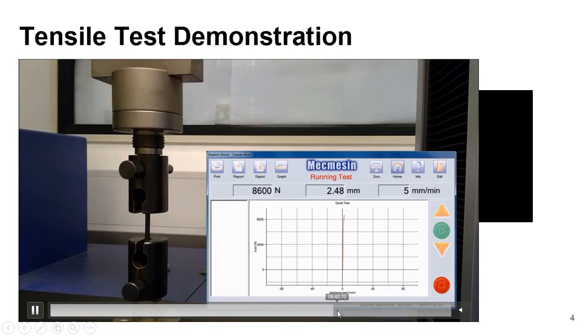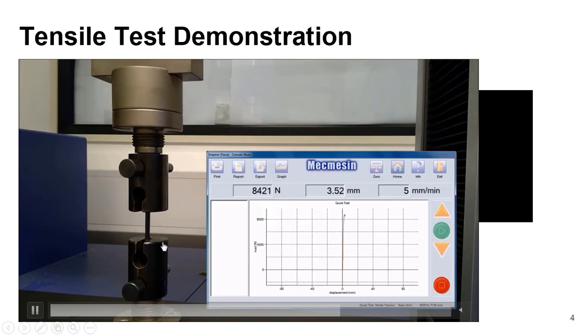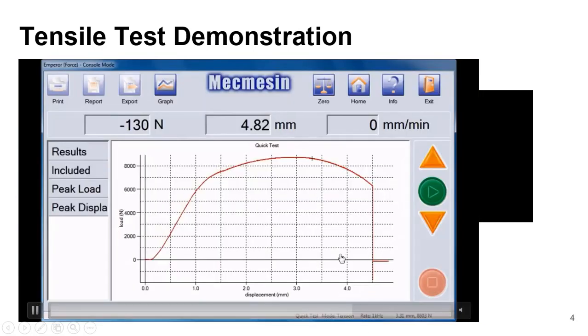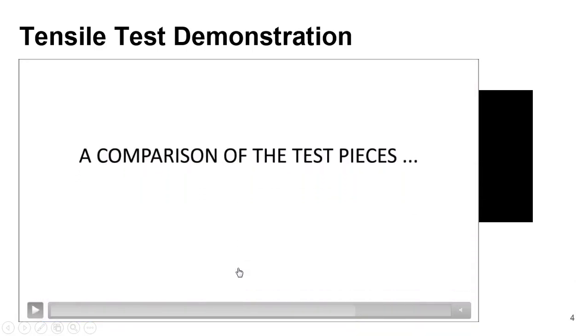Similarly, if we see the same experiment, the tensile test on a carbon steel, with 0.4% carbon in this steel. This is basically a ductile material again, and you will find that this is the stress strain diagram. If you just increase this scale, then it will look like this. So from here you get some idea.